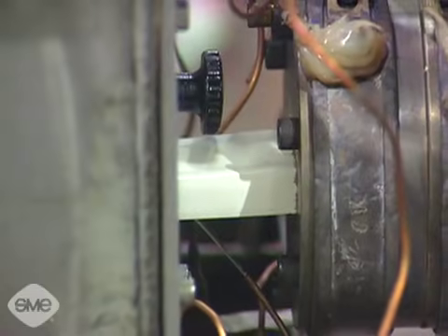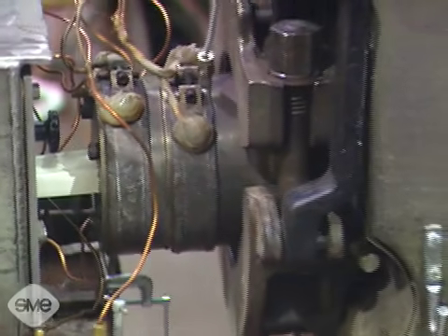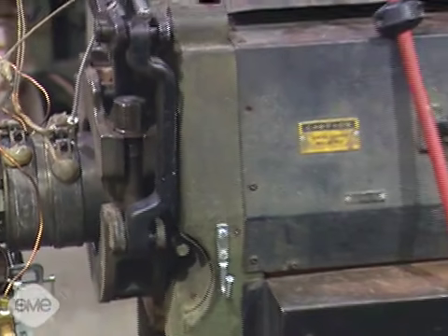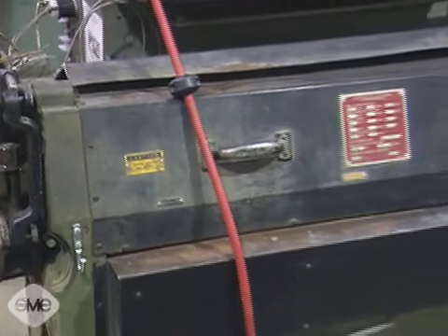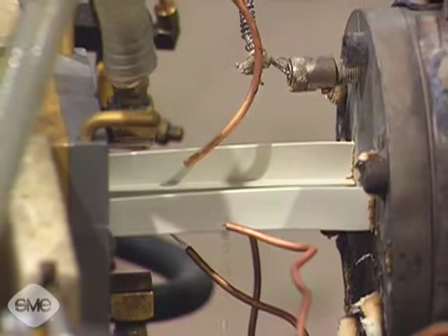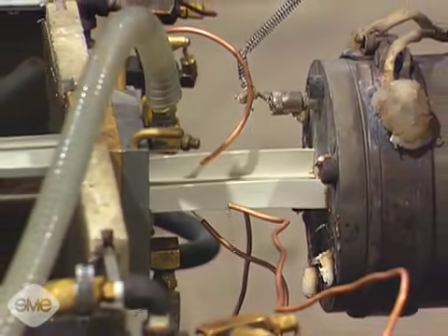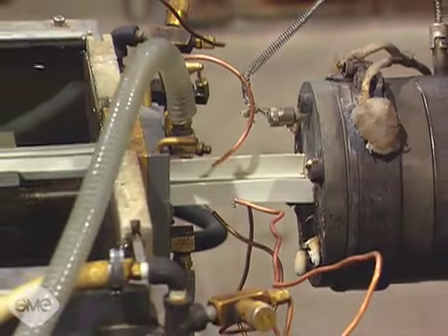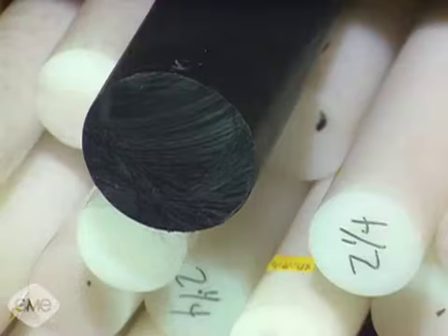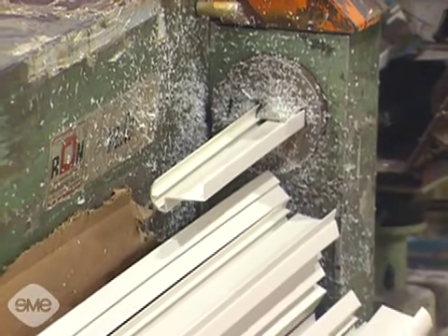Plastics extrusion is a continuous process in which thermoplastic feedstock material in an extruder is transformed into a molten, viscous fluid using heat and mechanical shearing. This thermoplastic fluid is then forced through a die opening where it is shaped and cooled into solid form. These forms include bar and rod, tube and pipe, or profiles such as angles and other cross-sections.